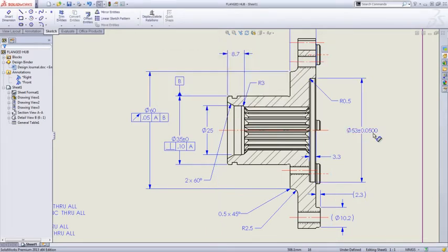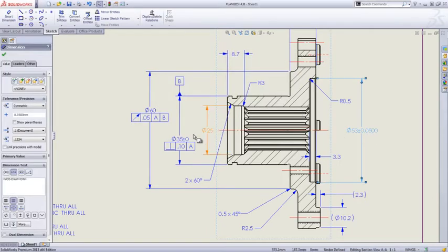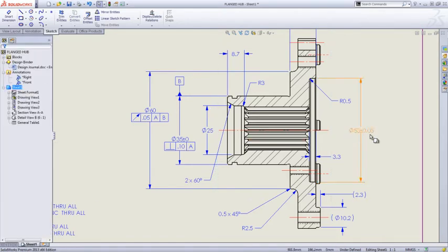Notice that the precision on the tolerance of this dimension is quite high, which can drive up the cost to machine this pocket. You now have the option to link the precision of the dimension and tolerance with the model, which ensures that changes are reflected in both places.